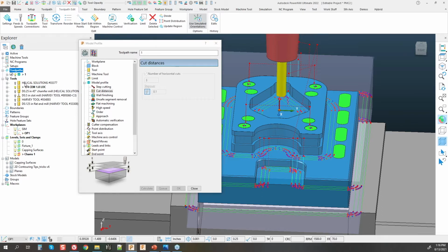I do prefer, however, to make copies of toolpaths for things like that because I like to separate things out in my NC program a little bit. But other than that, that capability is here, along with wall finishing and being able to come in and separate that step over for an individual pass. And you can tick last pass only. So we have lots of 2D capability in here, including cutter radius compensation applications, all right? So we can apply cutter radius compensation to this within ToolWare.